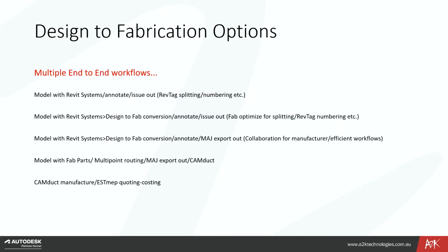You can minimize your detailing to elevations, duct sizes, and item numbers. So radiuses of bends, etc., will pass through to the manufacturer.